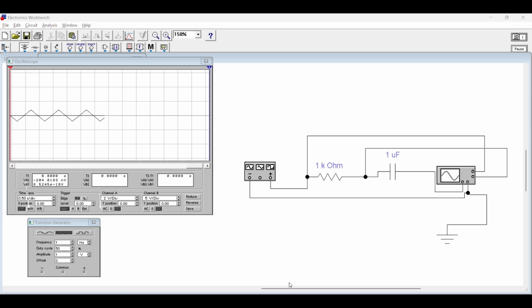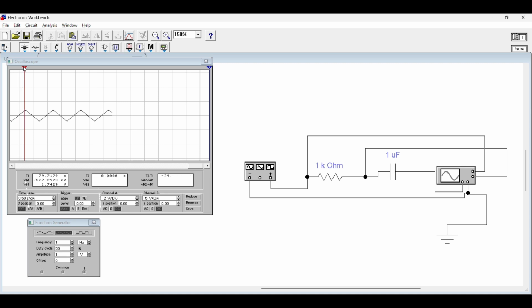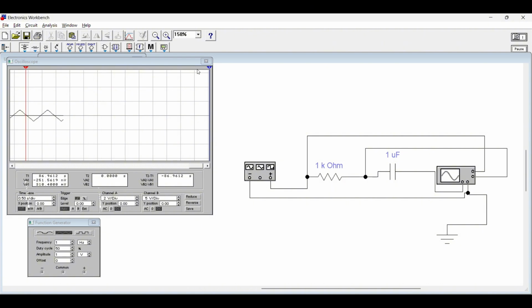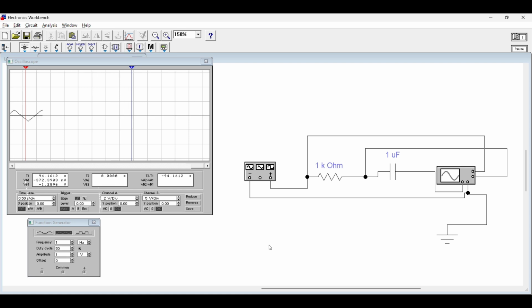slowly it cycles. To make time shifting, we use a resistor and capacitor connected in series to form an RC circuit. This circuit creates a time delay by charging and discharging the capacitor, which shifts the waveform in time. The amount of shifting depends on the values of the resistor and capacitor used in the circuit, allowing control over how much the signal is delayed.